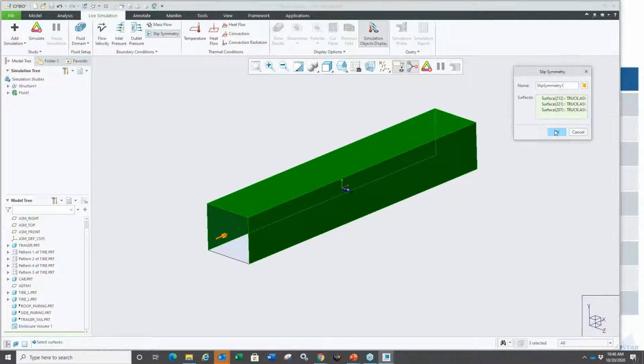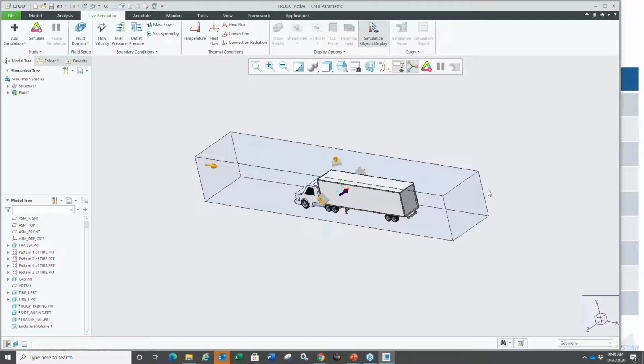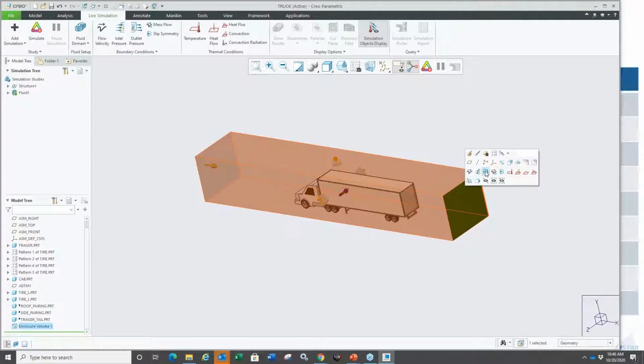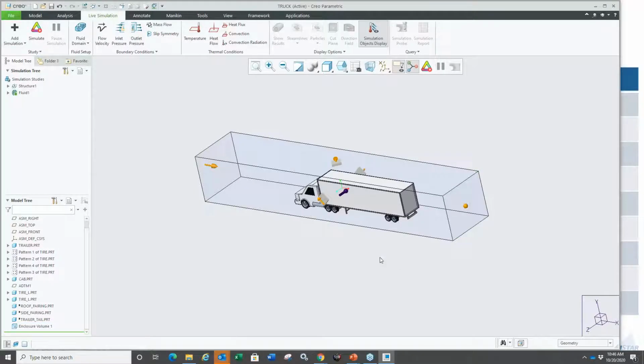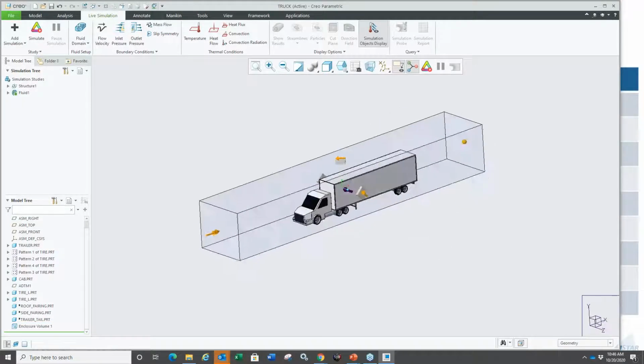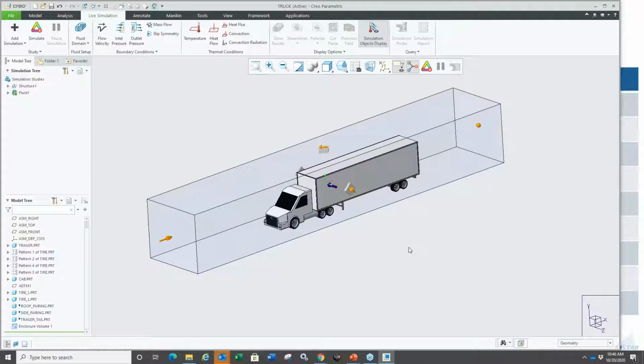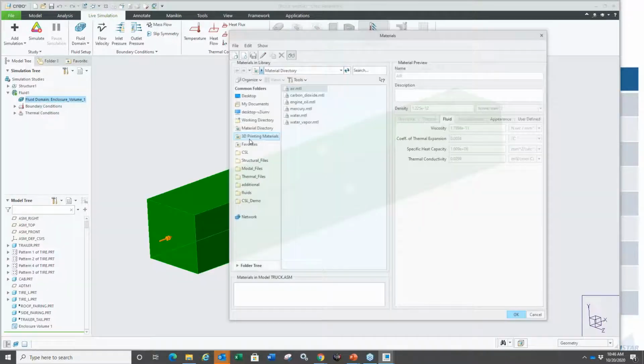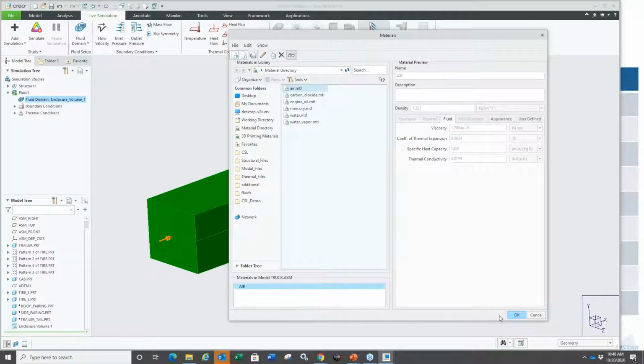So we'll just give it so it can flow through that, or at least along it, no friction there. So there it is. And I'm going to just specify a pressure of 0 here, and that's pretty much it, right? So of course I have to assign my material, right? We'll just give it air this time,